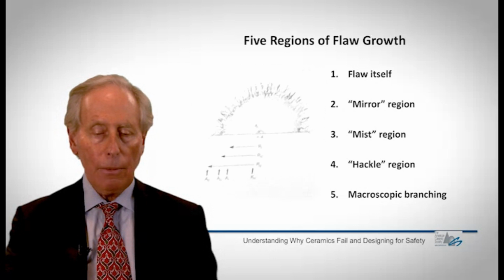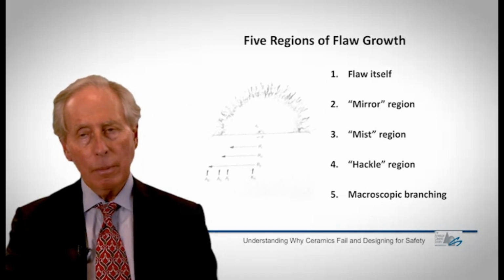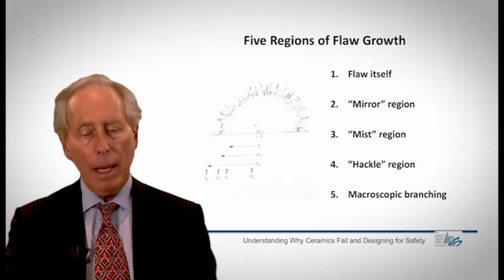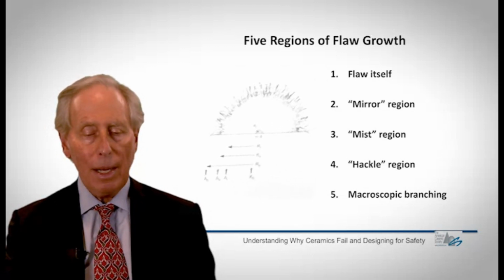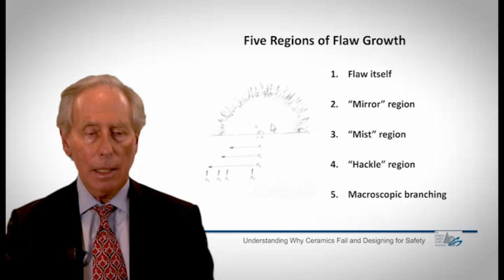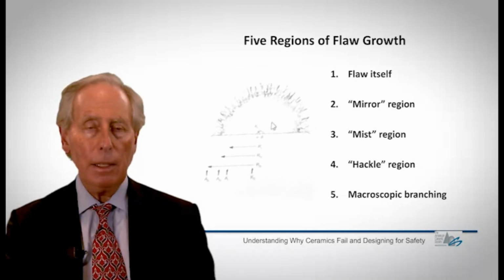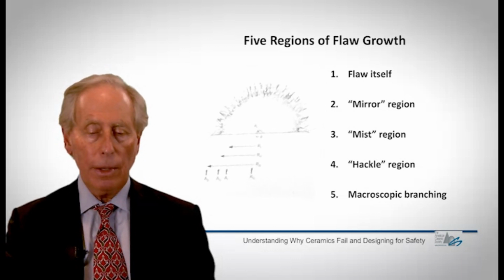I should point out further that depending on the size of the specimen and the stress level at which failure occurred, you may or may not see each of these regions. If the specimen is too small, then these cracks grow into a compressive region instead of a tensile region, and you won't see all or part of all these regimes. So one must realize that it's going to be material dependent and stress state dependent whether I can visually observe each of these regions.